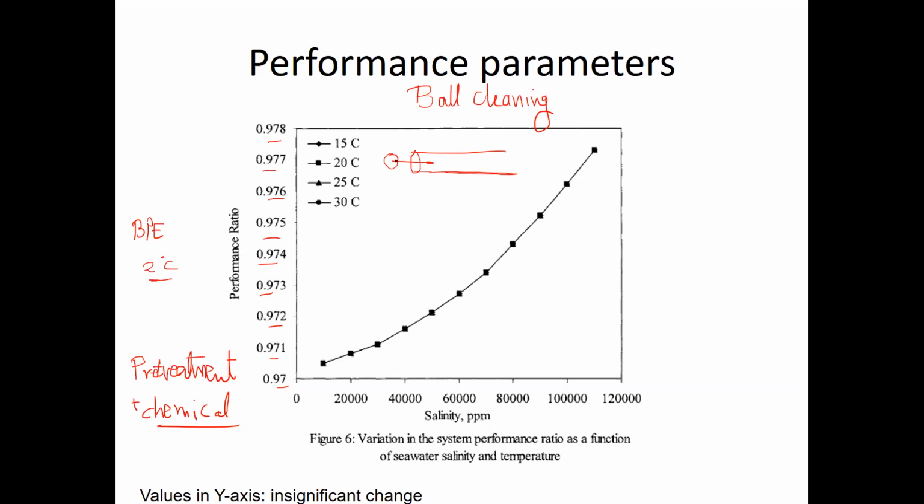There are pumps that are pumping the fluid in. As the balls are moving, they are making friction with the surface, so they are cleaning the surface. And this is very common. If you walk through any desalination system like the multi-stage flash units in Jubail, you can find these balls falling on the ground because they have lots of them and they are continuously using them. So that's something that you do, cleaning for the tubes while it is operating.